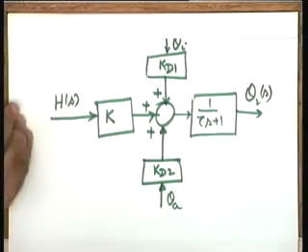Okay. This becomes the total block diagram of the system, and as I said, this becomes the plant model of the system. Any plant model I will say is complete for the study of control systems if you give me the controlled variable, that is the manipulated variable which finally your controller will activate, and the disturbance variables as the input, and the particular attribute of interest as the output, and it is well connected by suitable dynamical blocks, the transfer function blocks, that is the plant model.